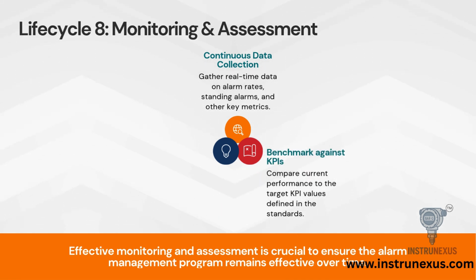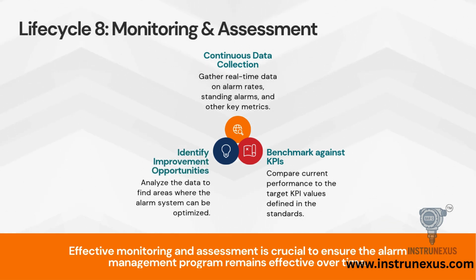Are we seeing too many alarms per hour? Is one specific tag responsible for 50% of our activations? By analyzing this data, we identify improvement opportunities. This closes the loop and helps us identify areas that might need to go back through the rationalization process.